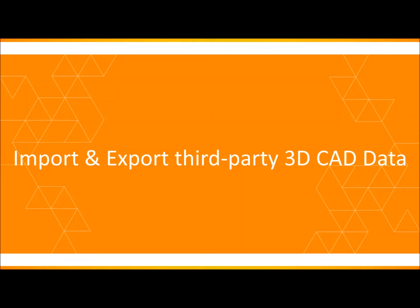Over the course of the last two major releases of Inventor, Autodesk have put in place some major under-the-hood additions to the toolset available when working with provided 3D models. This functionality is known as AnyCAD, and with this latest release we see the inclusion of AnyCAD 2.0. The main change between this and the 2016 release is the inclusion of a reference option for step files. This means that whereas in the 2016 release you could only convert this file format to a part file, you now have the ability to create a reference back to the source third-party file.